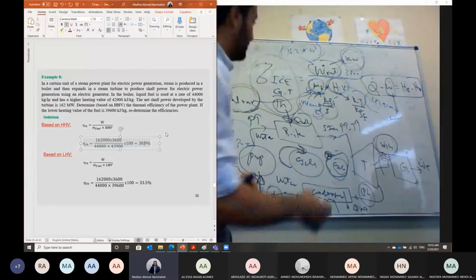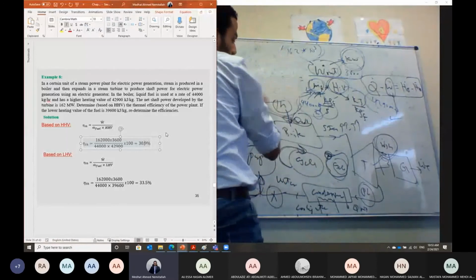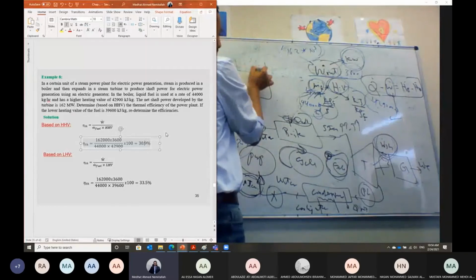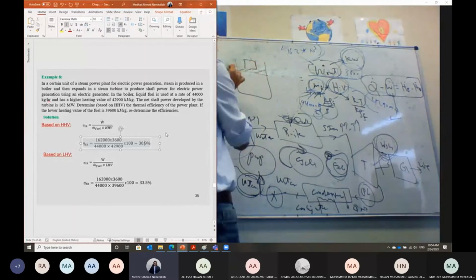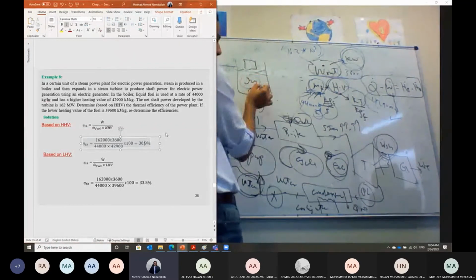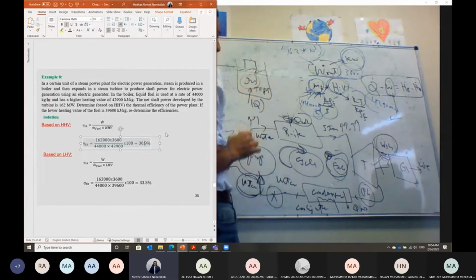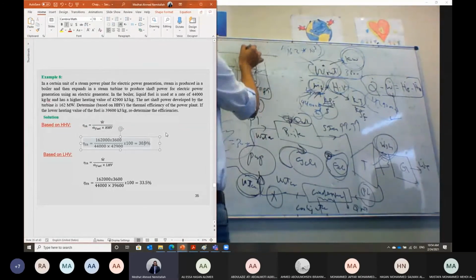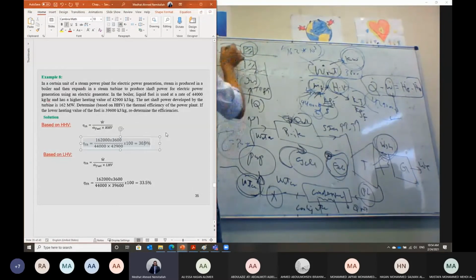A simple example of this, the concept of operation of working on a cycle. Let's say I have here a piston cylinder device, and I have loads here. I take this load at this level, I add heat here, so that we have a gas. When we add heat, the gas will expand, temperature will increase, pressure will increase, and that means we'll act with the pressure force here. This pressure force will raise the piston, and the load will be raised to this level. Then we can take this load. Now we did a job. We have raised this load from this level to this level.